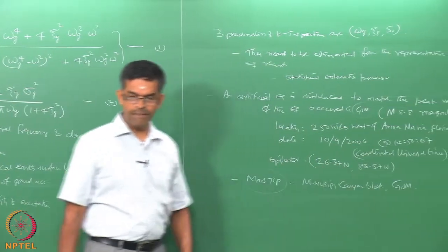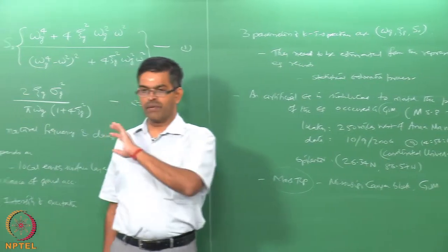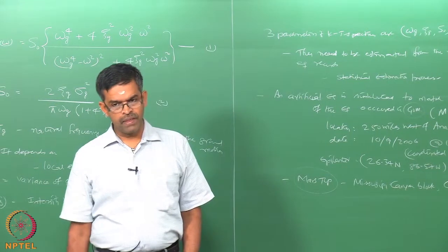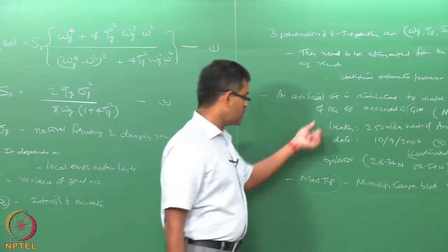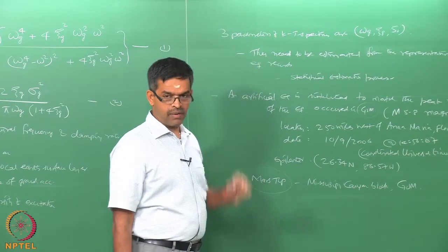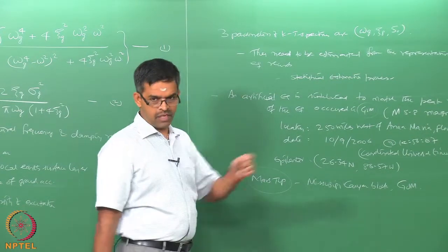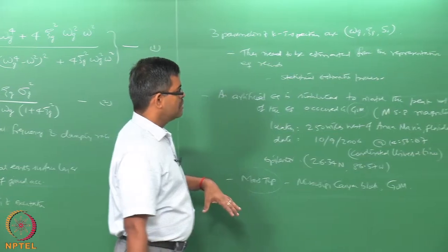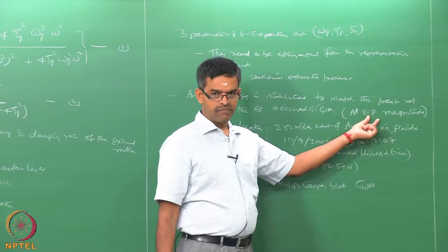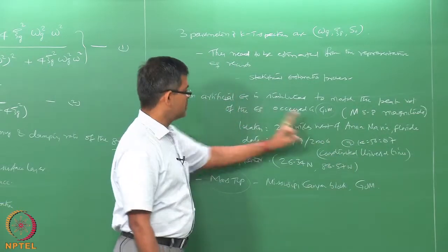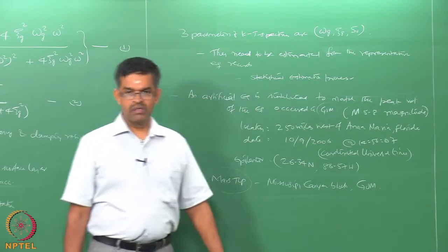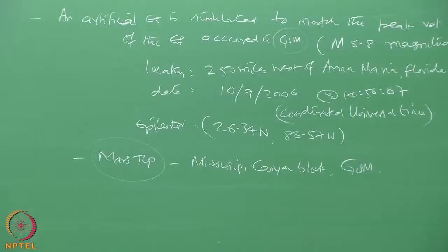So, in this study, distinctly high sea waves were created using modified PM spectrum and an earthquake signal was generated, simulated using Kanai-Tajimi spectrum, which I will show you will match with that of the measured signal intensity. And of course, the location is as close to the epicenter of this particular TLP. Okay.